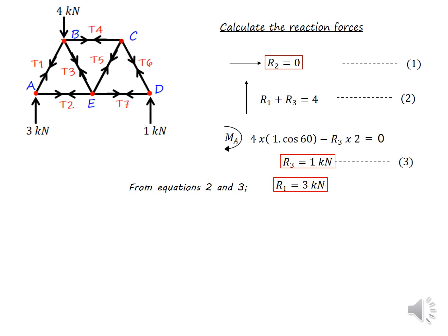So I marked all the member forces as tensile forces, but this is only an assumption. If you prefer to mark the member forces as compression, no problem. But once you get the answer, you will realize whether actually the member is under compression or tension, right? For the way that I calculate the member forces, I just marked all the members as tensile forces.